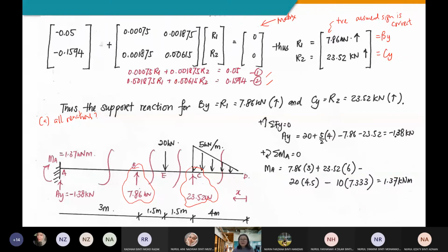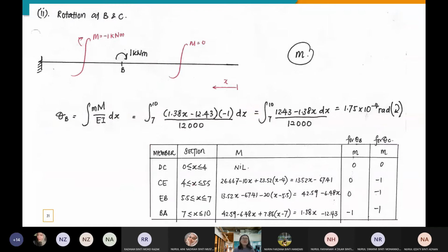But we have one more question to share. What if you need to determine the displacement of this indeterminate system? Of course, you need to solve for A first. You need to solve for the redundant forces in the indeterminate system before you can move to determine the displacement. So this question 2 is not about the flexibility method. It is about your virtual work method.